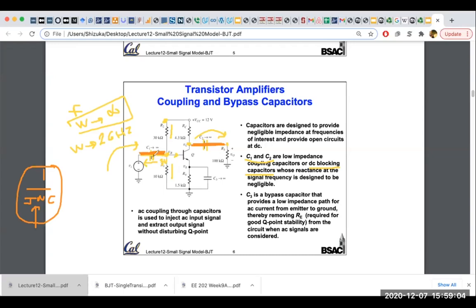But it's not easy to put big capacitances in actual RF microelectronics. In discrete amplification, yeah, you can do that. But when you design the chips, it's not really easy to design these caps so big, because they create their own resonant frequency and so on. They have their intrinsic parasitics. But that's another problem. So now we know what these caps do.